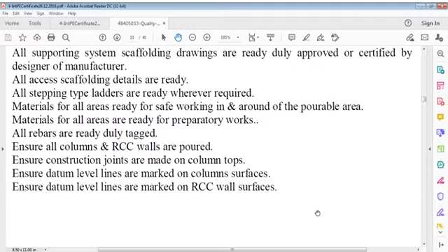Previous concrete is taken out, chipped, and any smooth surface has to be removed. All laitance requires to be removed from the column section, and it has to be done in a proper way. Unevenness has to go, and then you have to provide complete steel where bars are already there. You have to place shutters, and whatever bars you have to insert at the junction of column and beam, those bars are to be placed along with the main reinforcement. It should be clearly done.